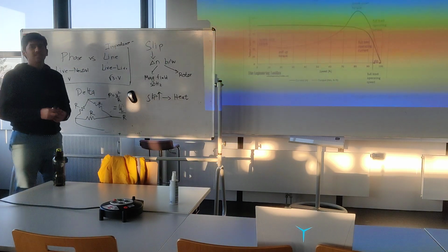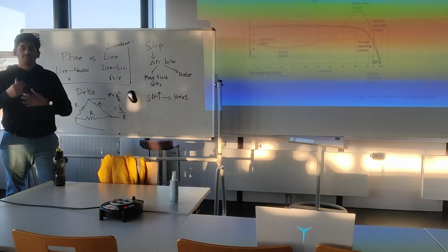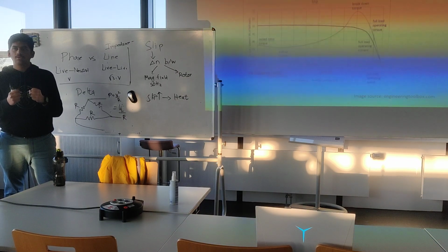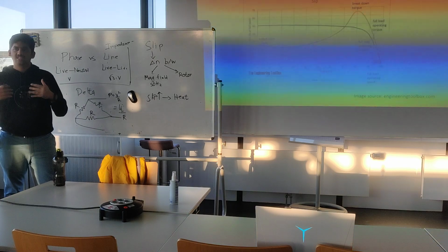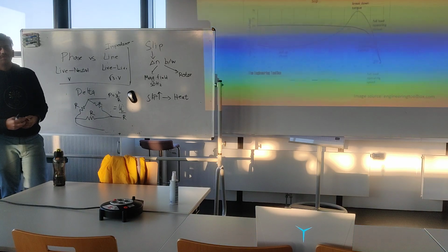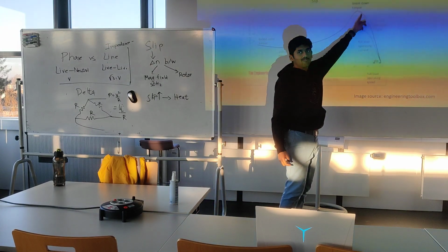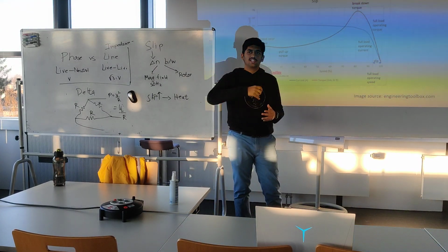So electric motors are limited by their ability to dissipate heat. Because the coils are so tightly wound, they have a lot of limitations in how much heat they can dissipate. So if you use them at this high point, you can do that only for a short period of time. You can use it as peak current.